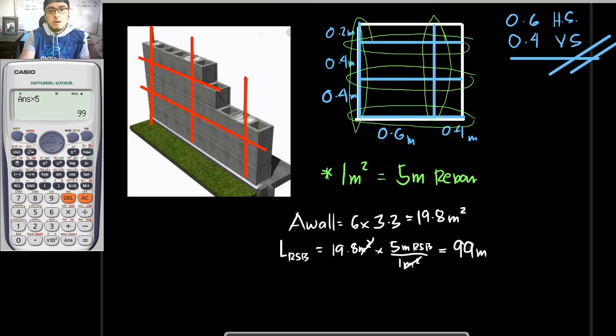So, length for RSB. But, by the way, guys, this wouldn't be your answer kasi dapat mag-increase tayo ng 10% sa length. Why would that be the case? So, that 10% that we would be increasing would account the splicing of bars. Because, in real life, if you are to splice the rebars, it wouldn't be like this.